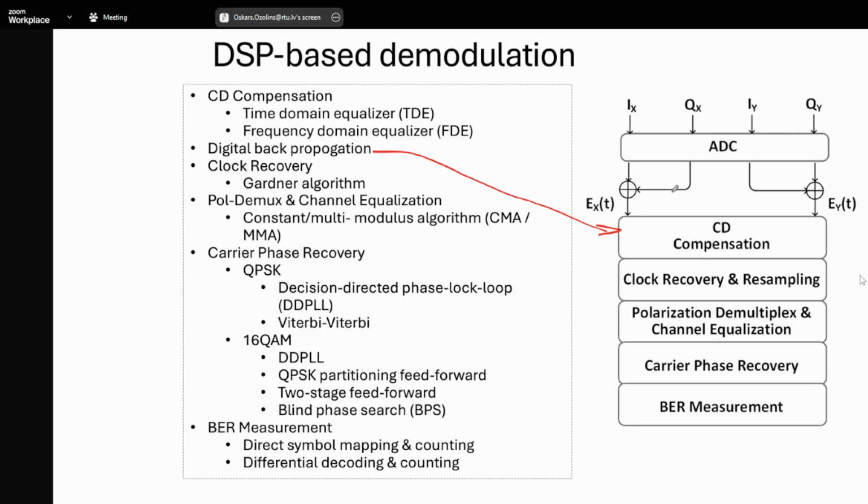In principle, at the receiver one could do the inverse solution of this Manakov equation, and then you can compensate not only chromatic dispersion in the link, but also resolve linear and nonlinear effects in a fiber. So digital backpropagation is being used to compensate for some nonlinearities, but then you really need to know exactly how the fiber is made, where you have all the losses, and what the coefficients are.